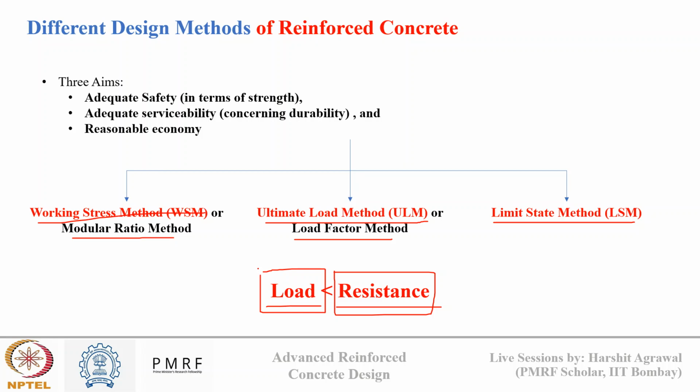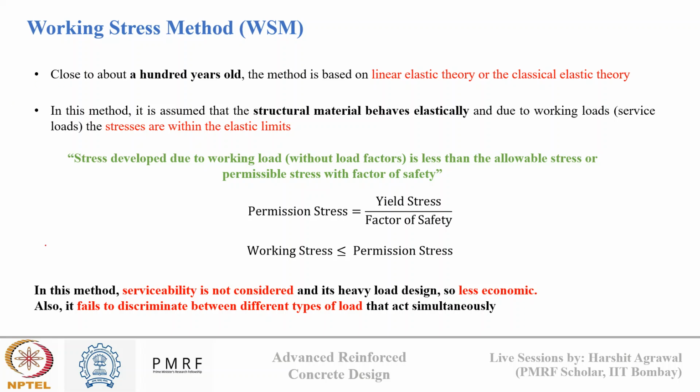Okay, so let's see what is the difference between these three methods. First is the working stress method. It is close to about 100 years old, and the method is based on linear elastic theory, or classical elastic theory. What we mean by linear elastic theory is that we are assuming both concrete and steel to behave elastically under service load. That is the basis of linear elastic theory. Both materials are behaving elastically under the service load.